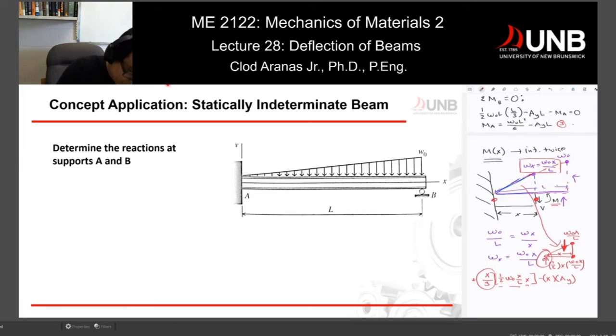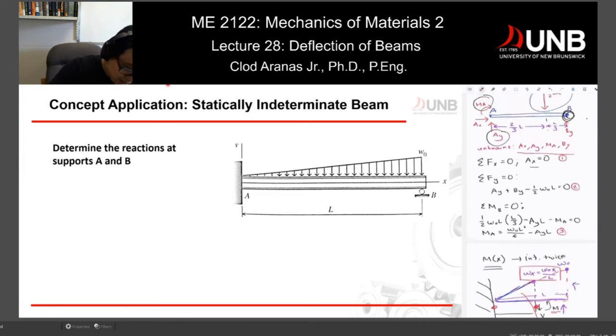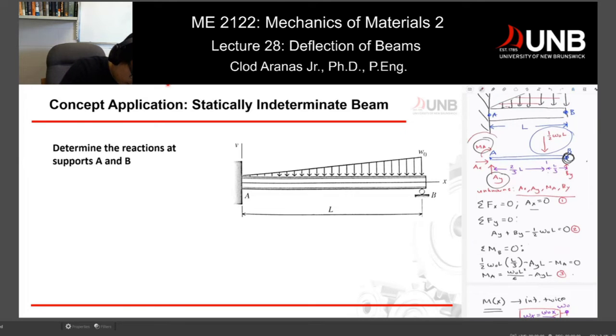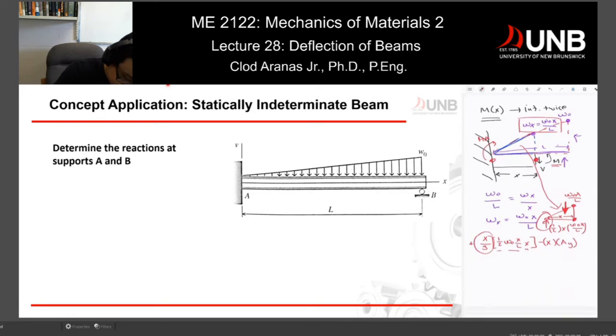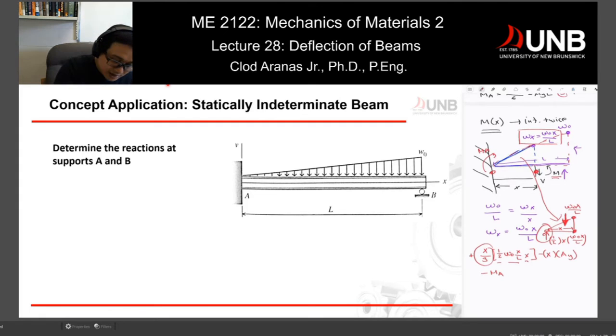Now, your moment, which we assume on the top, so if you go up here, M sub A right here, we have M sub A, which is a negative number. So this equation has negative M sub A. And take note, it's continuous. It just doesn't fit in the screen. So minus M sub A. Now, you have a moment right here plus, because that's positive, M, and that's equal to 0.